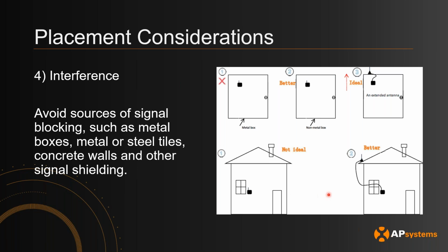Normally, if you have a multi-story residential home, it's generally okay from a microinverter communication perspective. But if you have a larger commercial building where the roof is really high and it's harder to reach those microinverters, then you may want to think about putting the ECU on the roof or having an antenna extending out.